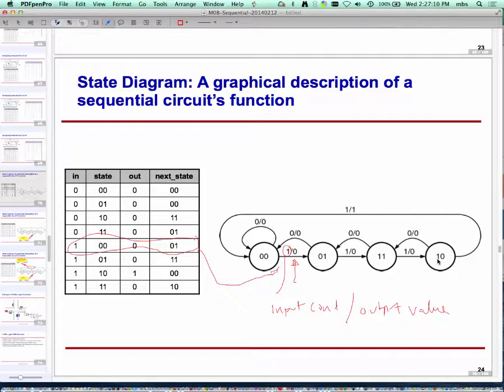You start putting in variables, much like we do in a program. So for really complex state machines, you either write them as a program and then the tool gives you the hardware from it, or you do it visually but also introduce some program variables. You'll find these kinds of tools if you go into this industry where more complicated state machines are designed. There is no way you're going to write down all those states as bubbles. It just doesn't work that way.